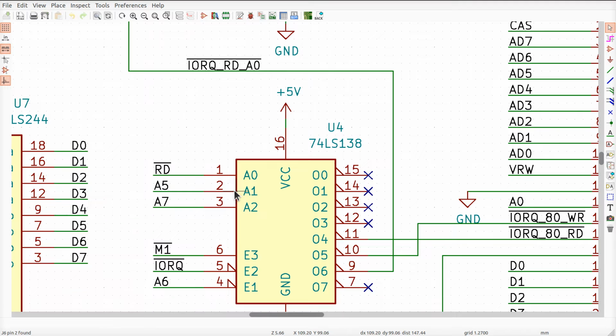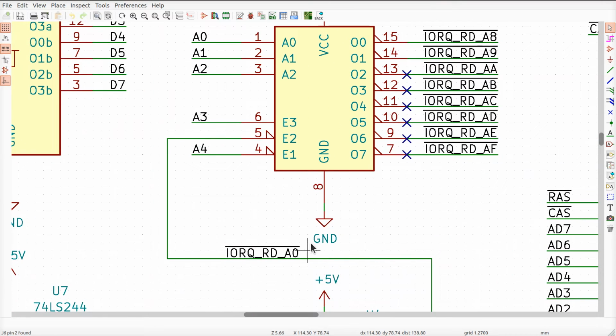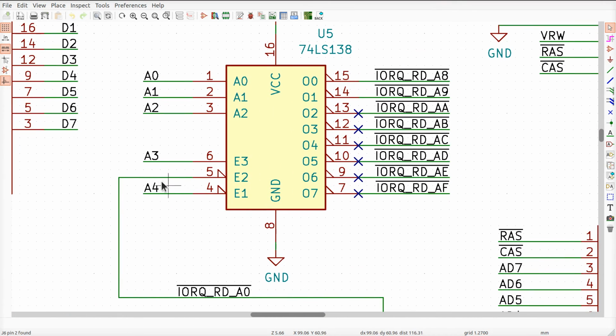Yes. Okay? That's when this will go true, and that represents the addresses that start from A0 and end at BF, as I've said repeatedly already. So if we then decode the rest of the address lines, and we say A4 must always be low, A3 must always be high. Why did I do that? Because these are unused enable pins, and I didn't want to waste more port numbers than I really had to. And then I got A2, A1, and A0 hooked down to here.